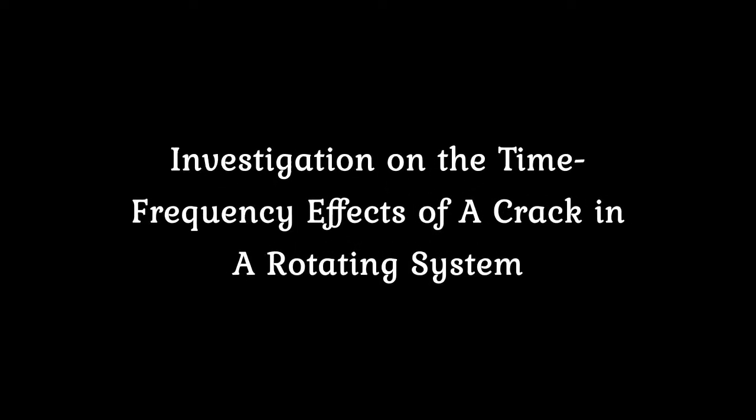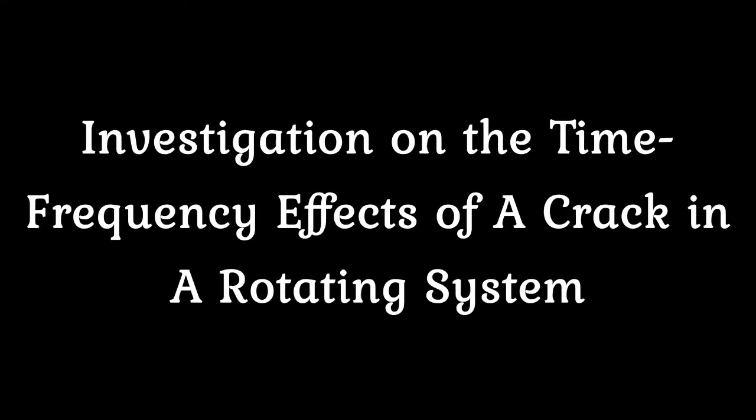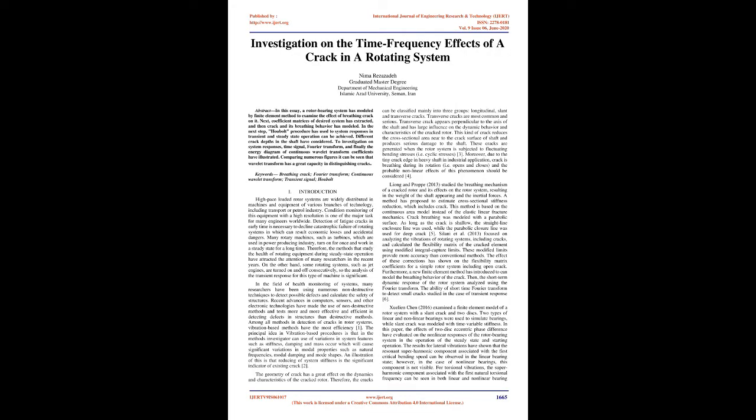Investigation on the time-frequency effects of a crack in a rotating system. Abstract. In this essay, a rotor-bearing system has been modeled by the finite element method to examine the effect of a breathing crack on it. Next, coefficient matrices of the desired system have been extracted, and then the crack and its breathing behavior have been modeled.